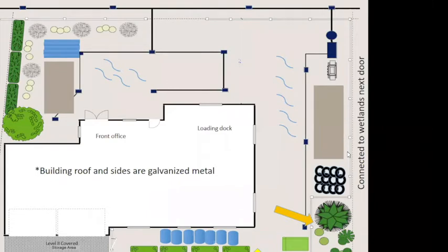Okay, so you've got a couple of unpaved areas here. What would you do with that? Put curbs around them, for one. Perhaps you'd want to pave it so that it's not putting gravel dust or soil onto the rest of your pavement, which would cause you problems with your stormwater sampling.